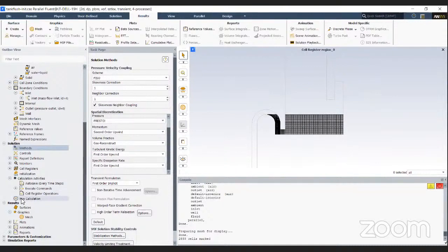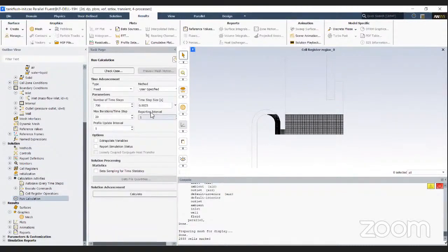So now that I've done that, I also want to see what time step size I want to assign so that I know exactly when my water is being stopped. Like I said earlier, after the first 100 time steps, change the inlet condition from a mass flow inlet to a pressure inlet. After 100 time steps, we would have 0.25 seconds, as you can see from the time step size. So that's when we're cutting off the water, right? We set it up accordingly.